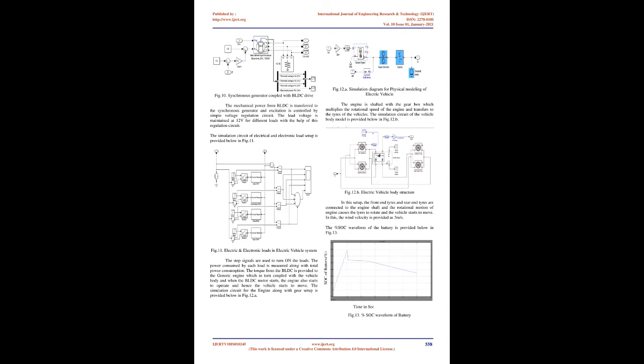Fig. 8: simulation circuit of BLDC drive. In this, the gate pulses are derived from the back EMF, which in turn is calculated based on the Hall sensor output signals. The speed control loop of the BLDC drive is provided below in Fig. 9. Fig. 9: simulation circuit for BLDC motor closed loop speed control.